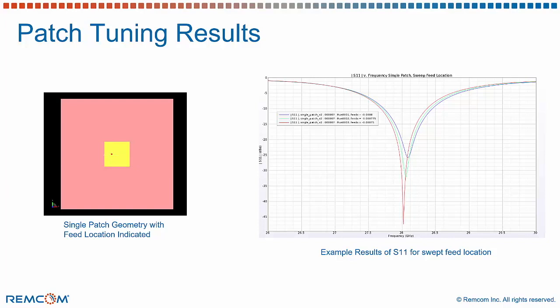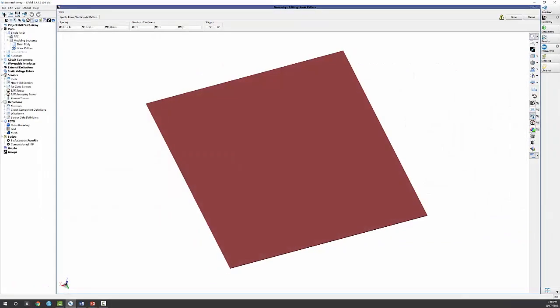I will switch to the XF UI to demonstrate this. The size of this ground plane is about 52 millimeters in both X and Y. Spacing between each element is predetermined. The number of instances that I will specify to create the 64 elements is 8 in the X direction and 8 in the Y direction. This gives us the ability to specify a 64 element array very quickly in the tool.